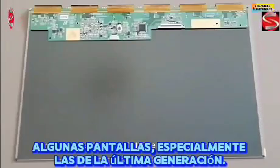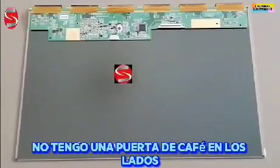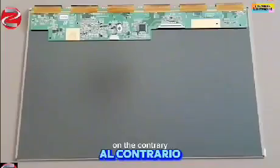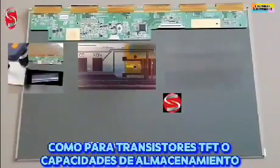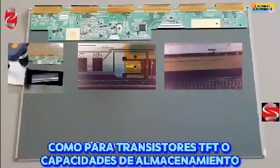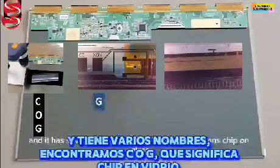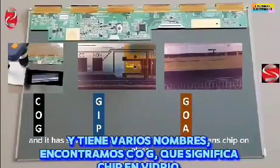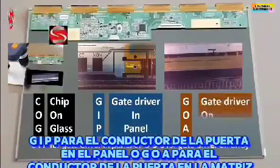Some screens, especially those of the last generation, do not have a COF gate on the sides. This does not mean that the screen does not have a gate driver. On the contrary, the chips exist and they are integrated directly into the panel, as for TFT transistors or storage capacities. This technology is currently favored in the manufacture of screens and it has several names. We find COG, which means chip on glass, GIP for gate driver in panel, or GOA for gate driver on array.